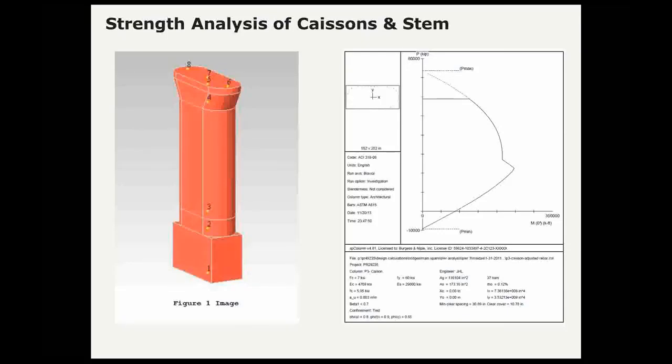That included all the various loads: the dead load and live load from the truss, the wind, barge impact loads, braking loads, and any loads coming also from the temporary pier construction. And then we created an axial moment interaction diagram here on the right, which we used PCA column to do, and used that to design the reinforcement in the caisson and in the pier encasement.